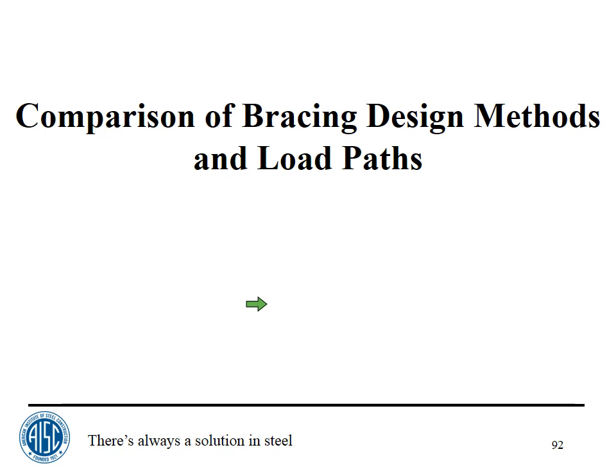Even for buckling, if something can pick up the load in a column so that it doesn't have to deform anymore, it will sustain the load at which it buckles, and the load can be distributed to other members. Anyway, this is reality. This is what happened. I can't explain it any other way. If I had a single column there, and the load was 400 kips when it was designed for 100, the building would have collapsed. But this thing was standing for 50 or 60 years, and there was no evidence whatsoever of any distress. Anyway, let's look further here.